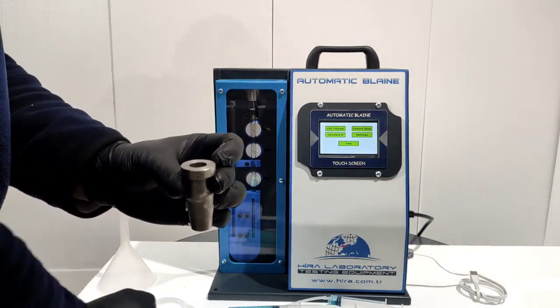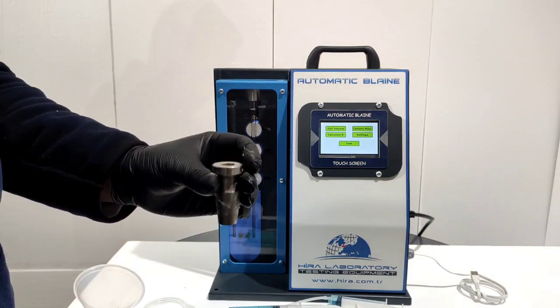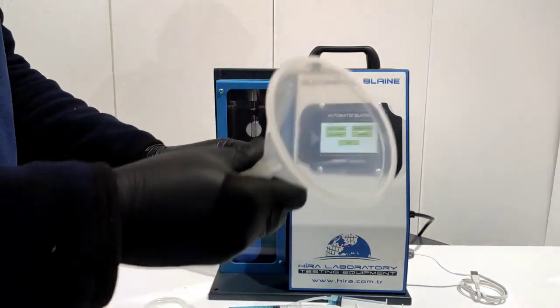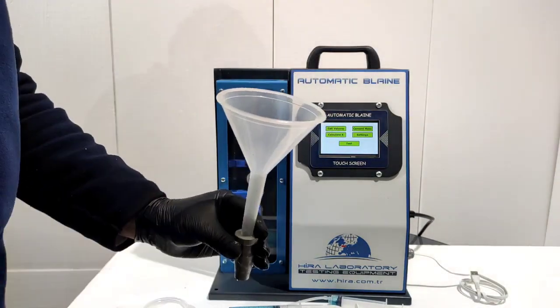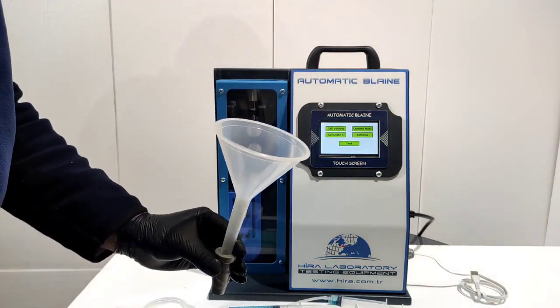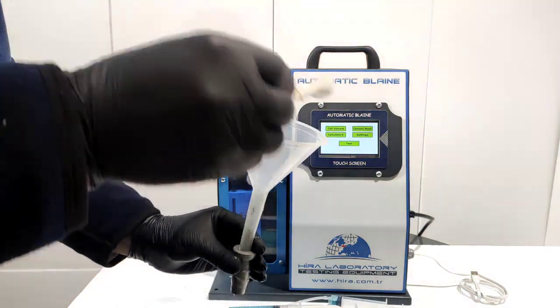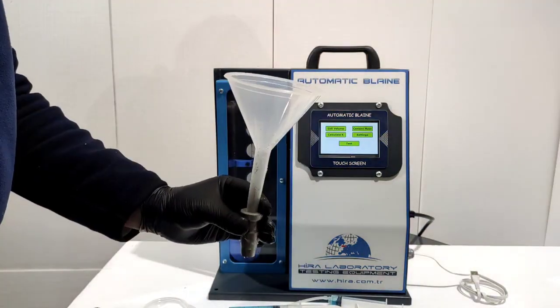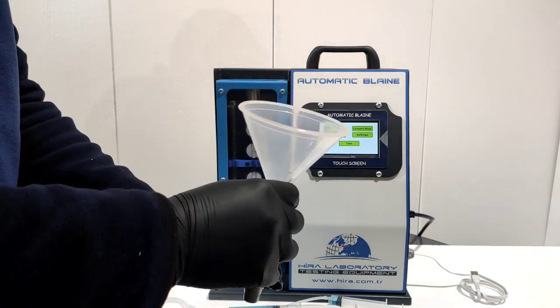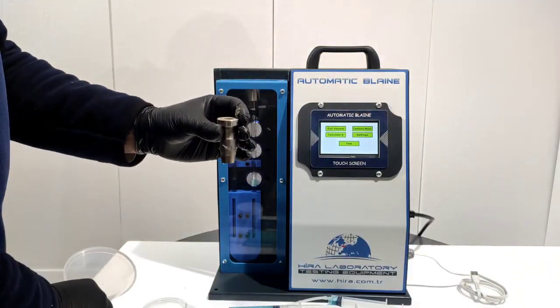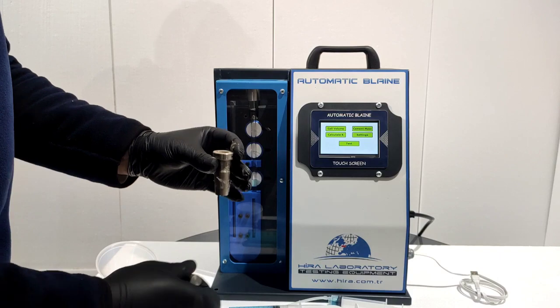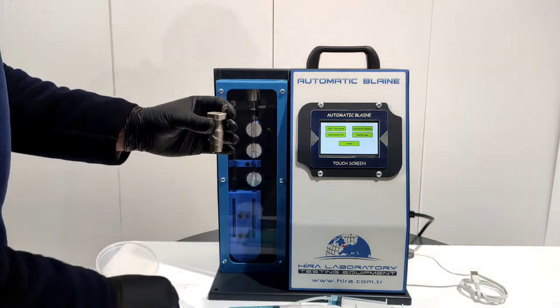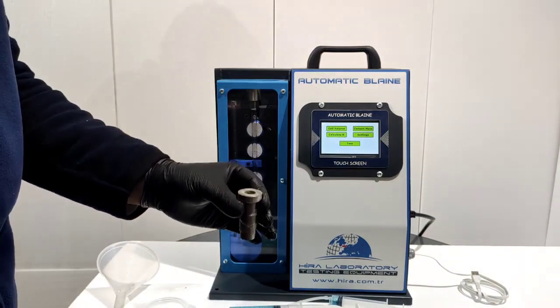Place the cell on a balance with an accuracy of 0.001 gram. Tare the scale. Fill the cell with the reference cement, as much as the M0 amount you found in the formula above. Take the cell off the scale and tap the sides with the mallet to stabilize it. Put the second filter paper in the cell and tamp it with the rammer.